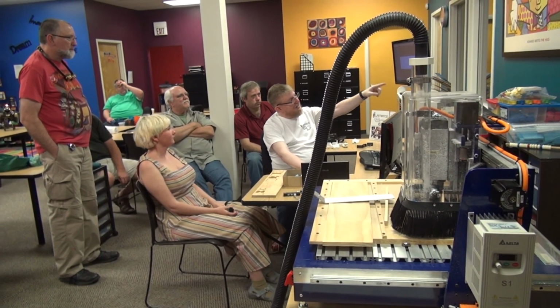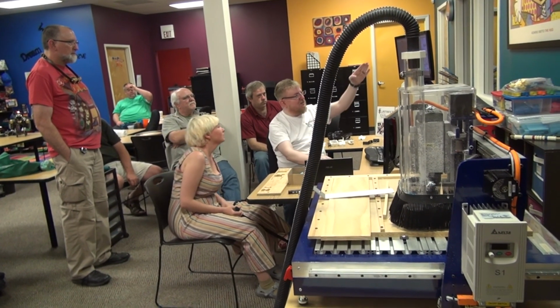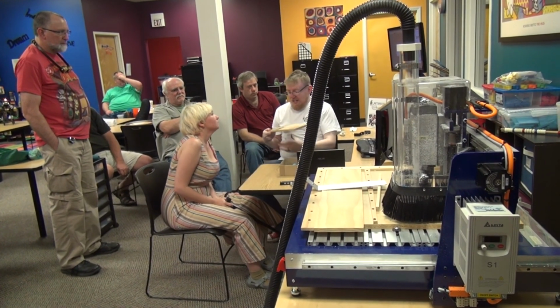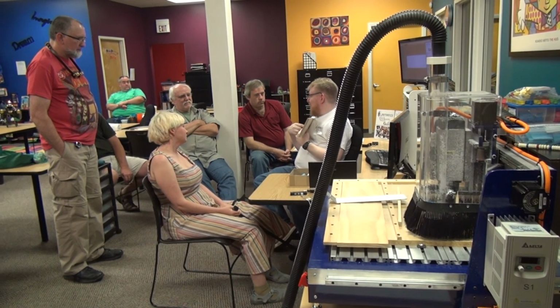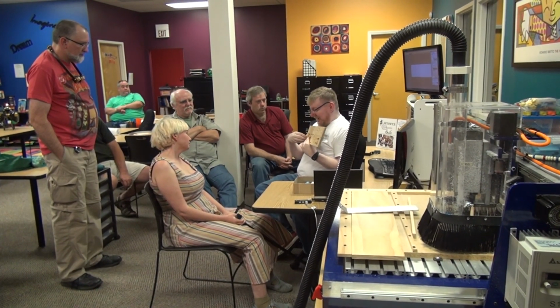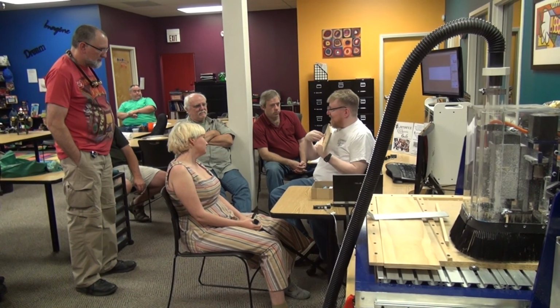And then this cutting depth tells me my starting depth and my cutting depth. Let's say I'd already machined this out and now I want to cut a hole in the bottom of this floor. Well, you do have to be smart enough to know that if I cut this out first and then I said cut the hole, it would start at 0 and it would machine in the air for a minute before it hit. That wastes time, it sits and lets your machine run. So you can tell it what depth to start cutting at for the next pass. So you do have to be aware of that to speed things along. But obviously, it's not smart enough to know what you're thinking, right? So it is better than it was.